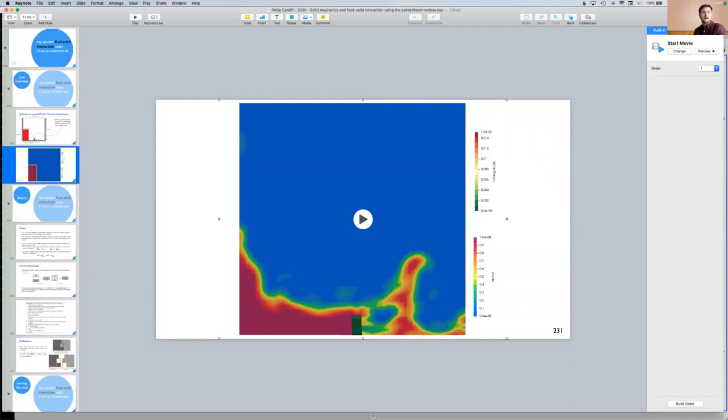So yes. In this case, the only information that the solid sees from the fluid is a force. It's basically just the force, whatever that force is. So it's two things, I guess, in fluids. It's the pressure force, and it is the viscous force, if a viscous force is present. So they're just transferred across, and then the solid will just move according to that.